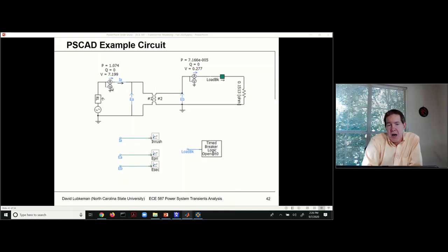There's actually a combi meter you can put in here, which is going to give you PQ, voltage, and a bunch of other quantities because you're taking both the current and the voltage measurement. And then I could either put a load on here or take the load off. For the Inrush, we're looking at an unloaded case, but if I wanted to check my model, I might decide to put some load on here just to see what I would get as far as voltage drop and everything else.